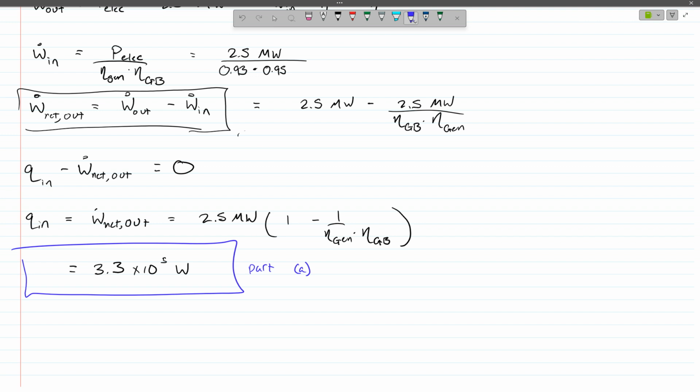The next question is, all right, that's a lot of power that needs to be dissipated to keep this thing from cooking itself. What does that turn into in terms of the rate of heat flux through the surface of our nacelle? The reason we might be interested in calculating that is that it gives us the link between what we're going to talk about later today, which are the modes and the rate equations for different types of heat transfer, and sizing our nacelle so that we can achieve a reasonable heat flux to make this happen.